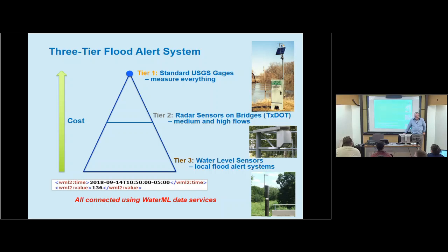Yes. National water model, what are the inputs that you have to provide? Well, it is an adjunct to the weather forecasting system. So it uses the outputs of weather forecasting, which are the predicted rainfall and predicted climate conditions. Those are the inputs. And then the water goes onto the land. There's a land atmosphere model that does surface water balancing and soil water balancing, which produces runoff, and then all the water's geographically transformed using the squares to catchments transform, like what we did in the Thiessen Polygon exercise, and then it's routed down the rivers. So precipitation and weather are the real inputs.